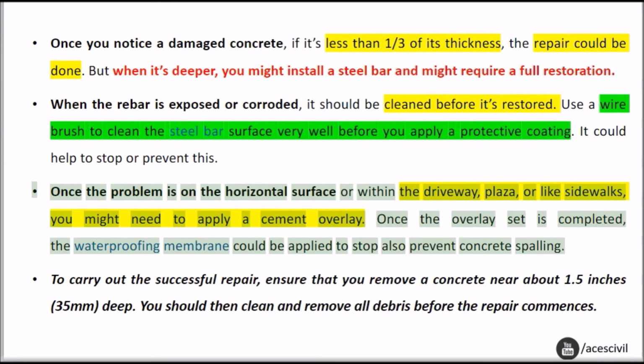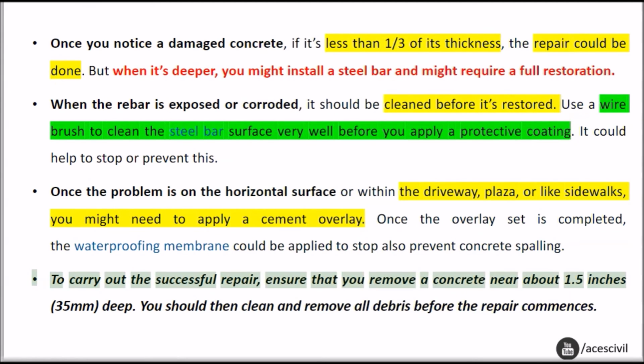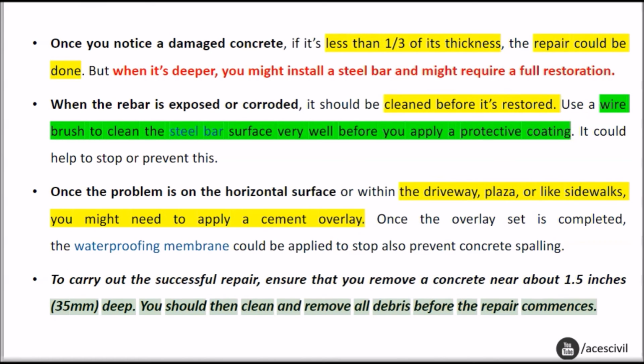Once the problem is on a horizontal surface such as a driveway, plaza, or sidewalk, you might need to apply a cement overlay. Once the overlay is set, a waterproofing membrane could be applied to also help prevent concrete spalling. To carry out a successful repair, ensure that you remove concrete about 1.5 inches, 35 mm, deep.